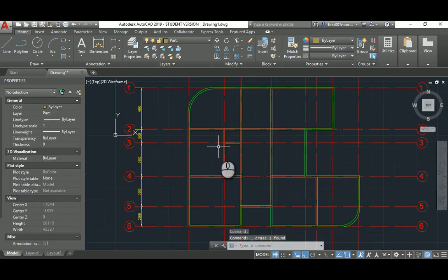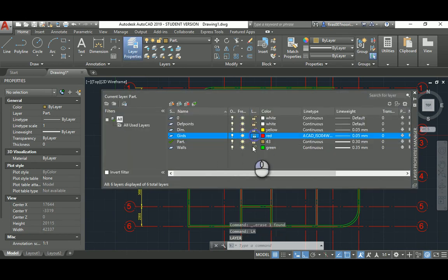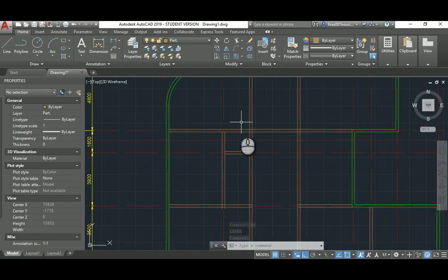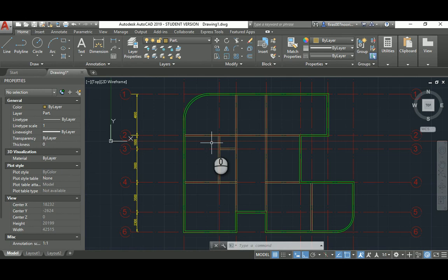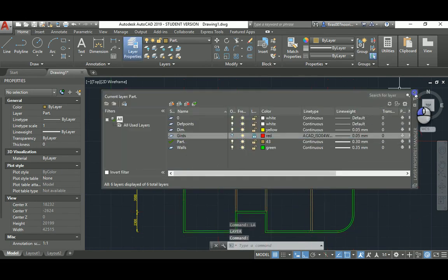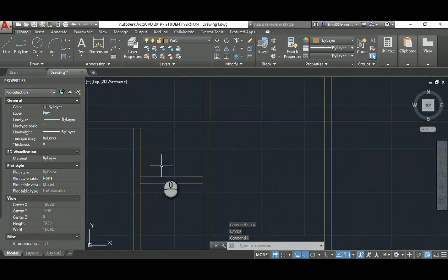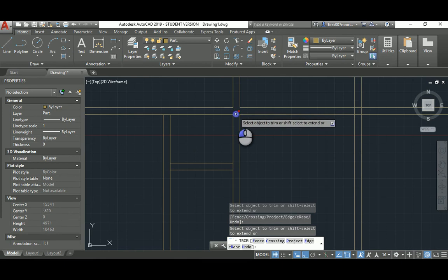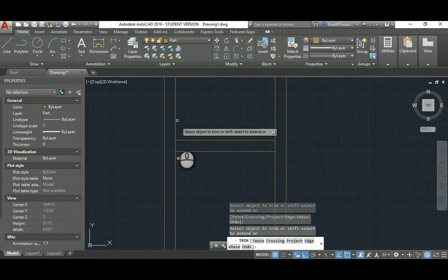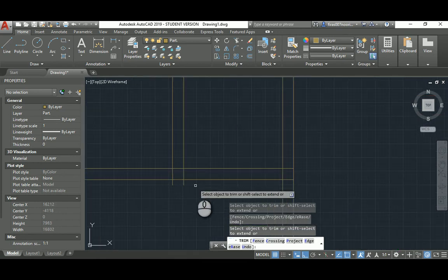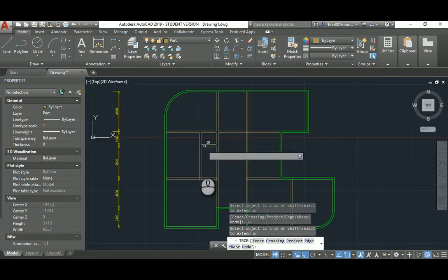So now it would be a really great idea if you lock the grid, so it's less painful when you want to trim and when you want to fix and open the doors. But probably it would be even better if we turn it off for now. So when you trim, TR space space, it would be easier to select 4 lines, 4 clicks instead of 8 here, 1 instead of 2, and so on. So that sounds good. Oh, let's fix this.